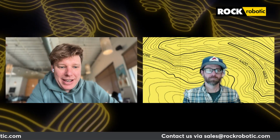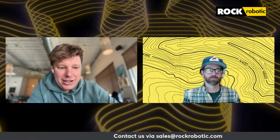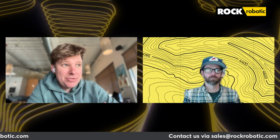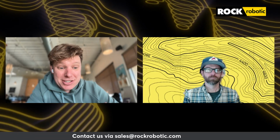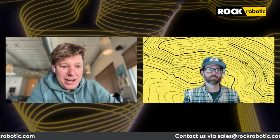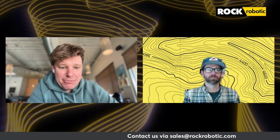Because at the core of it, internal to these pieces of hardware, are phenomenal quality components. The IMU is super high end. You have a triple band GNSS receiver, and we have the Rock bases, which use the same GNSS receiver inside. I compare it to the Trimble systems, and they do the same. And even the laser scanner does half a centimeter precision.